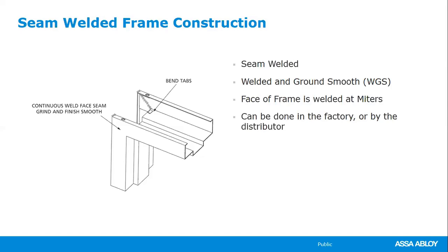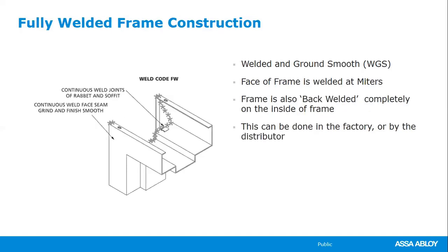If he doesn't specify and he just says welded, you want to give him just the standard weld that your shop guy or the service center can do. The other type of weld is where you'll see in specifications where they are concerned with sanitation, where there's a lot of moisture around, and they will call it out as a back welded. Sometimes you'll hear it specified as a continuously back welded frame.